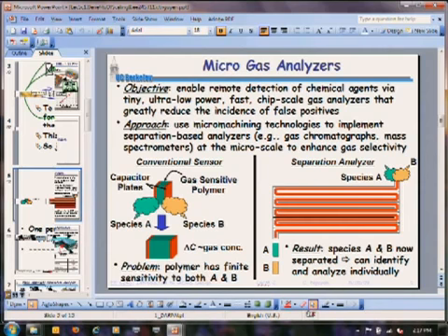They all have gas masks and stuff. They're not wearing them because they're uncomfortable. The sensor alarms, right? No one puts their gas mask on, right? Why is that? Because the sensor's done it before, and nothing was there, right? So the problem is false alarms, right? The sensor went off when that gas wasn't present, the horrible gas wasn't present, but some other gas that was very similar to that horrible gas made that sensor say, yes, that's what it was.